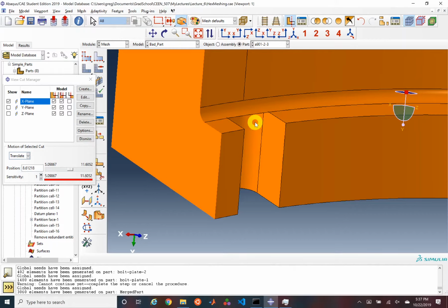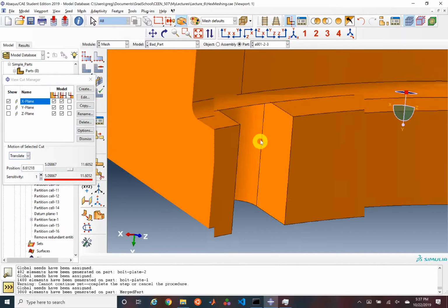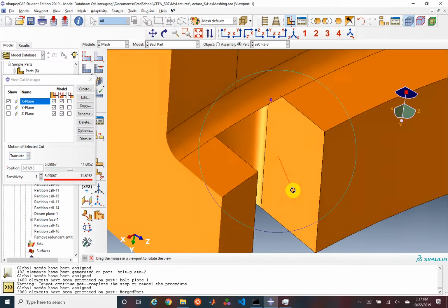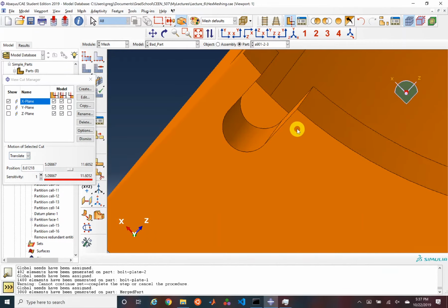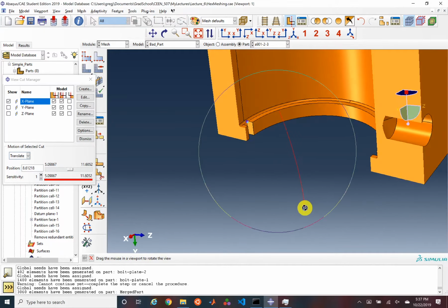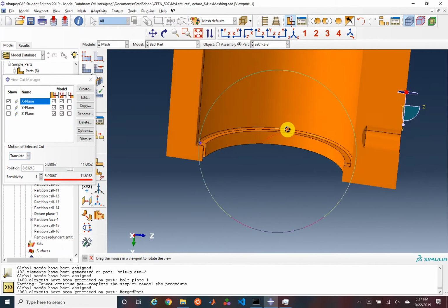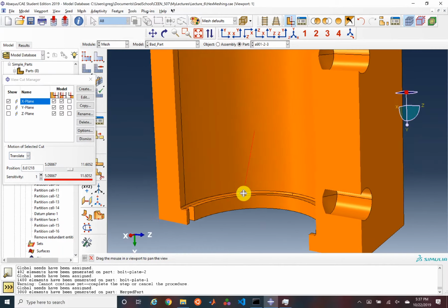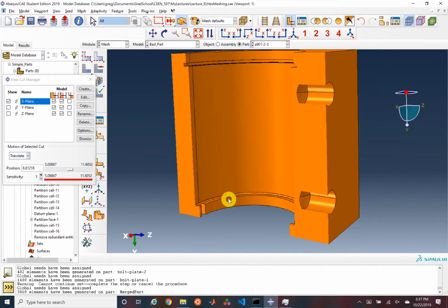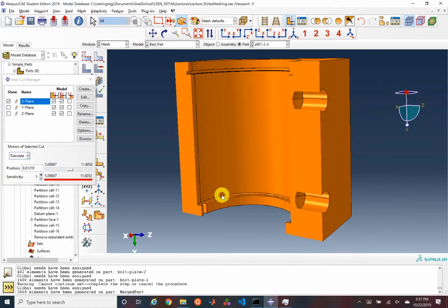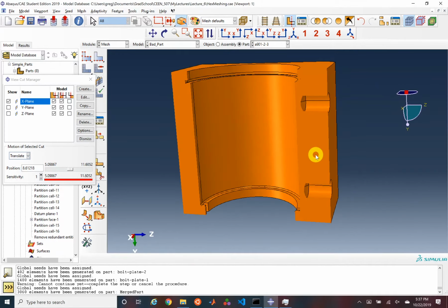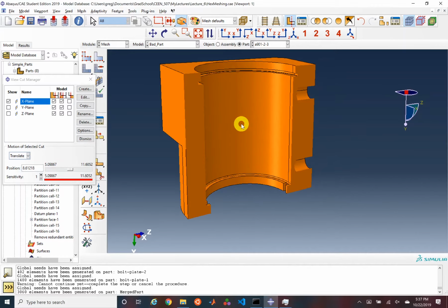And so what I have found is that in mesh generation, you are sometimes the front line of finding errors in part definitions, just because of the rigor that it requires to construct a hex mesh. And so, to be honest, I wouldn't even attempt to mesh this geometry. If I saw this at this point, I'm just sending this back to the designer and telling him, you've got a problem, and you need to fix this. So that's just a bit of a word of advice that I would give you.